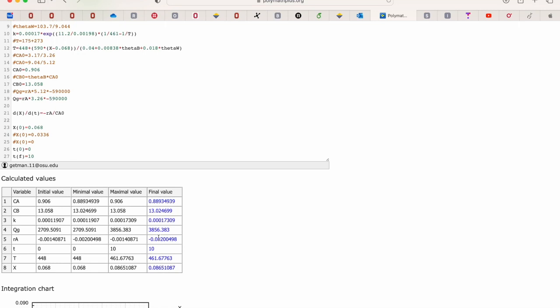So even though the heat exchanger failed for 10 minutes, once you get it running again, the conversion still hasn't increased enough such that the temperature is so hot that the heat exchanger can't control the reaction. The reaction can be quenched completely, or maybe even taken back to the desired temperature of 175 degrees C.